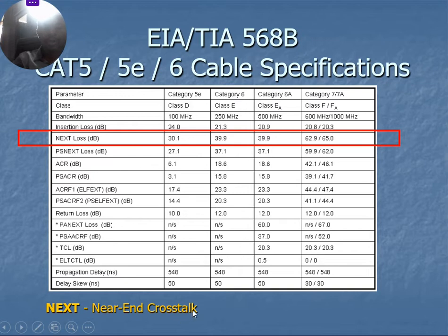Your voice signals are converted to current and they travel in wire. They don't travel in the form of voice or any physical parameter. They travel in the form of current. When you are talking on your telephone or network, it is all converted to electric current. And as they travel as current, you remember when current flows in a wire, an electromagnetic field is produced. This field, when it is adjacent to another wire, will reduce the voltage in that wire, which causes crosstalk in these wires.